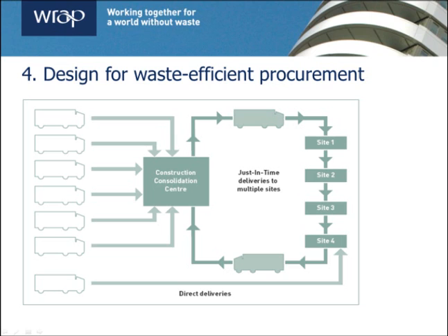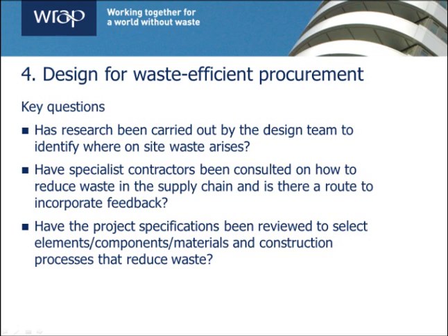For example, getting all first fix electrical work done before plasterboarding commences. On unusual projects, designers can require enabling works to be carried out first, improving overall project efficiency and reducing waste. In terms of key questions, it is important that research is carried out by designers. Firstly, designers should look at generic research on typical waste streams for the type of project and the associated wastage rates, and secondly, to assess the question of on-site waste generation for the particular development under consideration.